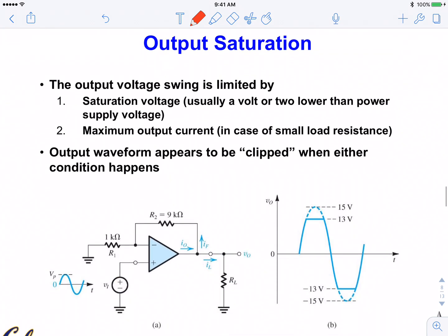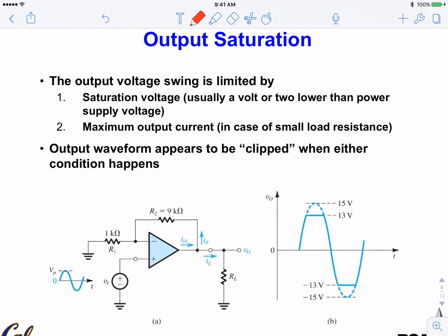All right, okay. So other nonlinear effects: output saturation. If you have touched any circuits, you all know signals saturate. In some cases, like digital circuits, we take advantage of that. We make them saturate, so they become bit 1. If they go to the bottom, they become bit 0. In the LTI system, linear time invariant system, we want to preserve their analog nature.